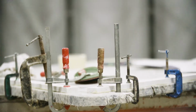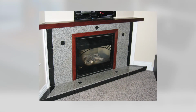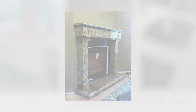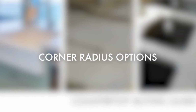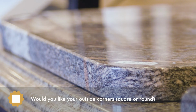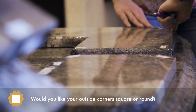It is generally not necessary to build up the edge profile with 3 centimeter material. Some materials, typically used in shower surrounds, fireplace surrounds, or decorative applications, can be as thin as 1 to 1.6 centimeters. Corner radius options. Corner radius refers to the degree of roundness the countertop corners will have. The larger the radius, the softer the corners will look.